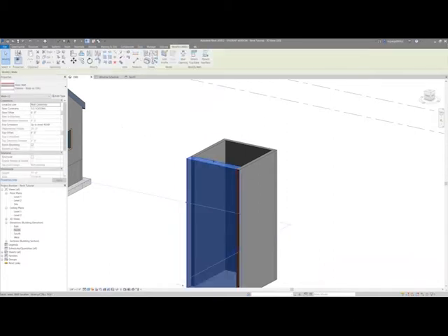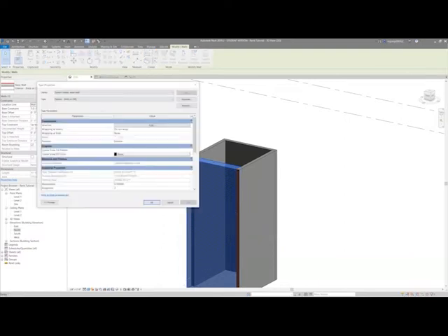So for right here, we're going to click on this wall type and go to edit type. All right. And so this is going to break down the family basically. So just so I don't screw up this type, this family is brick on CMU.